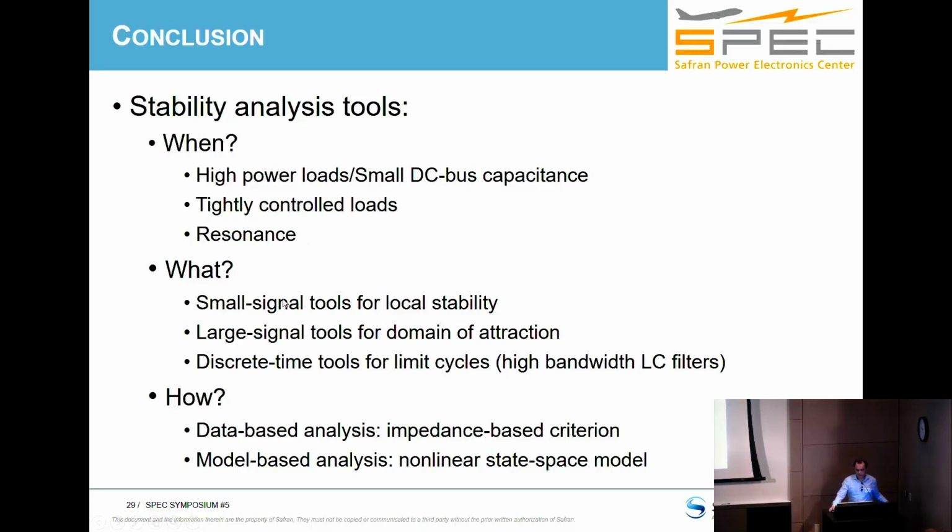What tool do you use? You can use small signal tools for local stability, and large signal tools for the domain of attraction. I didn't talk about it because I didn't have enough time, but you can even have discrete time tools in the case where your LC filter cutoff frequency is very high, comparable to the switching frequency. In that case, average modeling is no longer valid, so you have to develop other tools, and I'm talking about discrete time tools. And you might have data-based analysis or model-based analysis. I talked about them, so I'm not going to develop them.